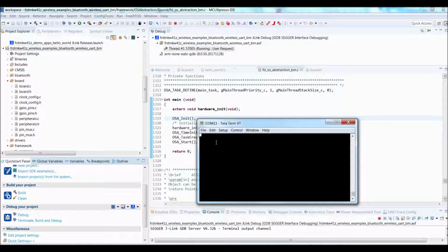I'm going to communicate to board 2. And board 2 came back, and I will type on here in caps, back. And so the second board worked. Okay, so I want to disconnect my tablet, and what I'm going to do is plug my first board in. Again, board number 2 is running the software out of the debugger. Board number 1 has it flashed, and so when I plug it in, all I'm going to get is a COM port for it, and then I'll be able to do the communication with it.